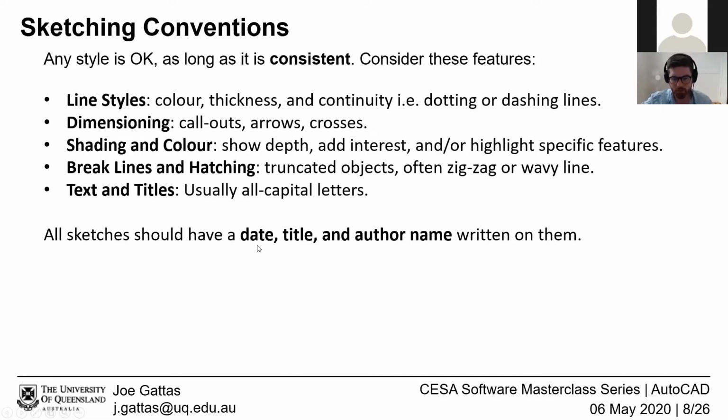The only golden rule is that if you're using this as a communication avenue as an engineer, you need to date, time, and author your sketch. So everything that you produce, if you're intending it as an email or a piece of professional or semi-professional communication, they need to have those three attributes to ensure it's trackable, and allow people to refer to a particular document. Particularly in an office context, they might go further and actually number a sketch with a project ID and then a sub-reference. That's excessive for your personal use.